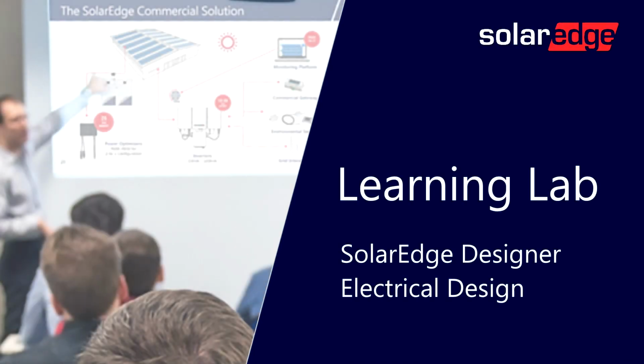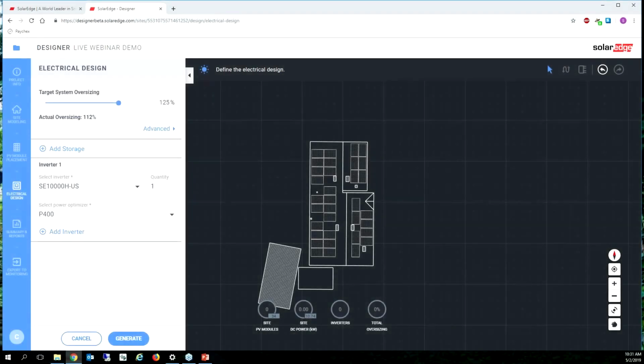I'm going to go ahead and click the electrical design, and we're going to string it. So first, the tool tells you to define the electrical design, and it says your default system DC to AC ratio is 125%. I can just use my slider and make it higher if I wanted to, say, 155%. And it's going to change the inverter based on my DC to AC ratio. So at 125, the tool is recommending that I use an SE10000H, and at 155, it recommends I use a 7600H.